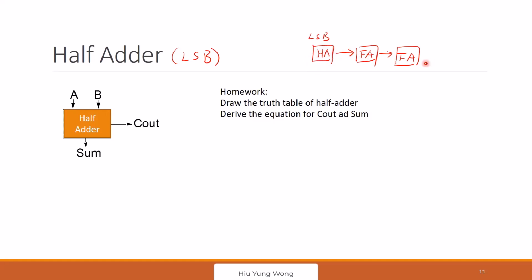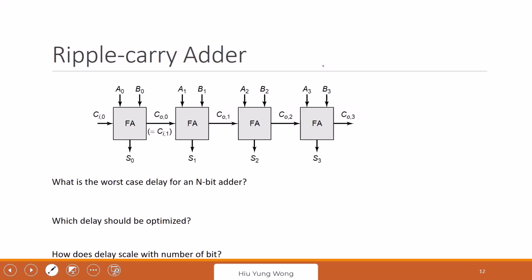Make sense? So in your project, you can just create a full adder cell and then just cascade them, but that will waste your time. If you are more meticulous, more careful, for the first bit you may use a half adder to save area. But do it yourself at home, right?